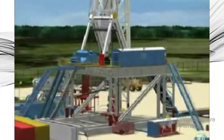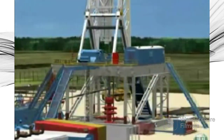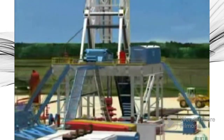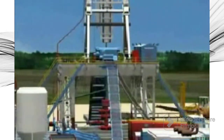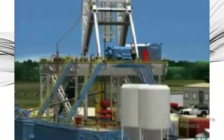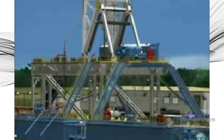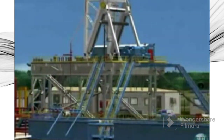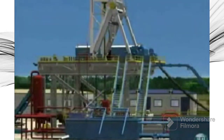Rig operation continues 24 hours a day, 7 days a week, closing only one day for Christmas. Two shifts of complete drilling crews are assigned for the entire drilling project. Drilling happens in stages: drilling, running in casing, cementing, and then drilling again until the bit reaches TD, or total depth, is achieved.